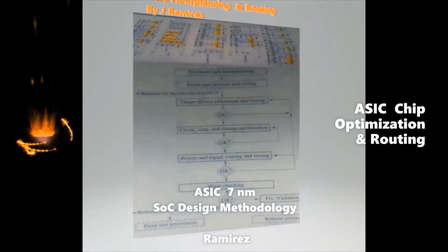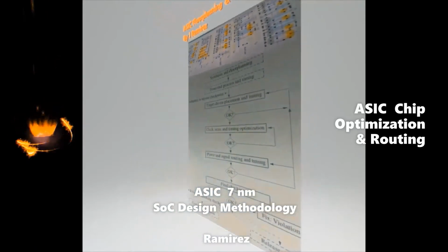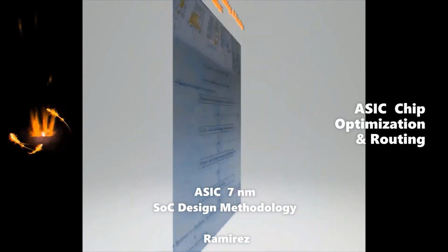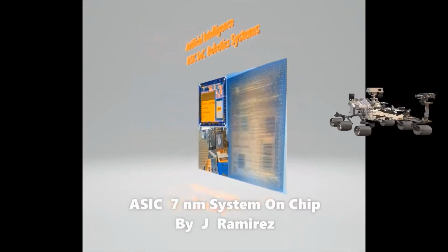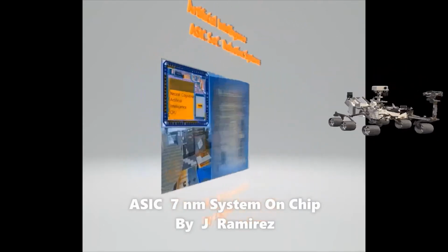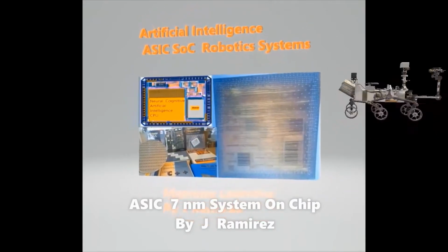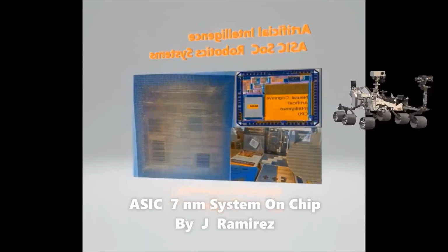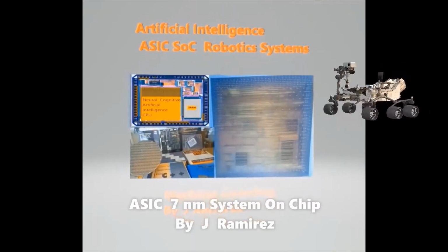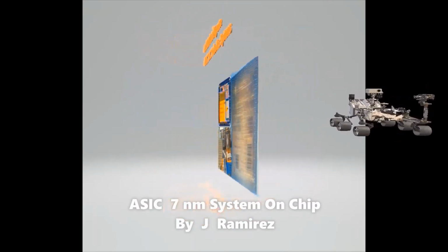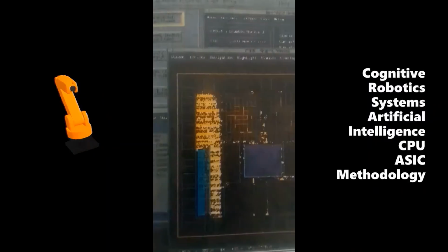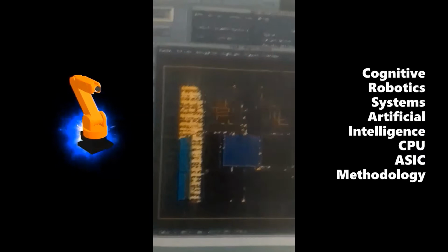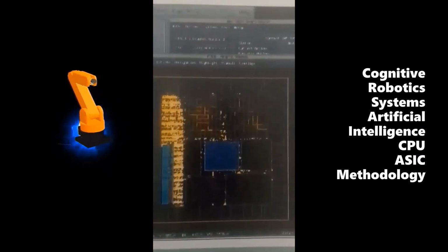Three, perform an initial placement to determine an improved basis for constraint generation, and optionally to fix the placement of large objects. Fourth, generate new constraints for placement on the basis of a timing analysis done using wire load and RC delay values derived from the initial placement.